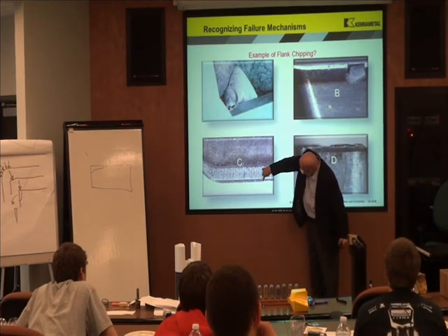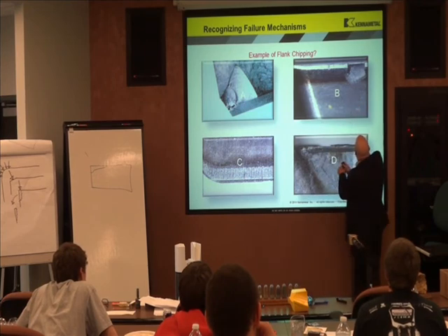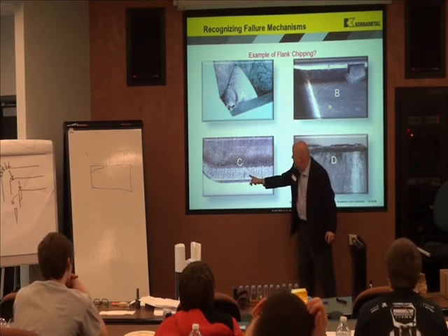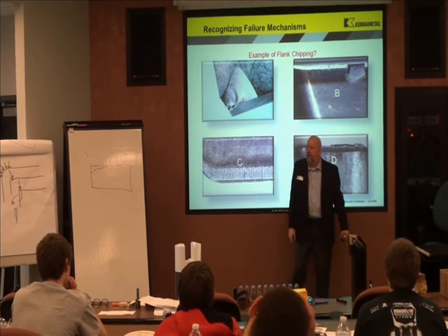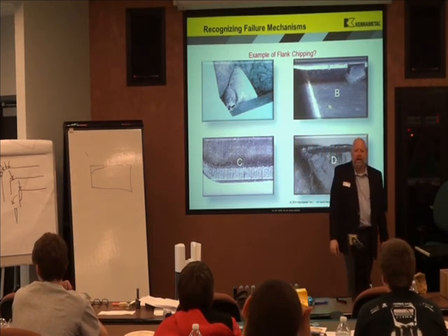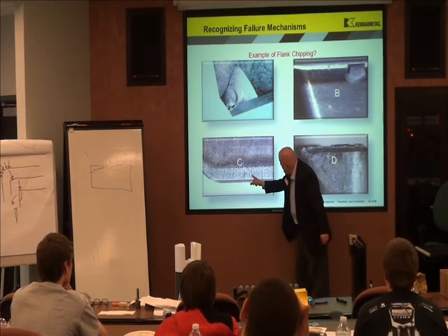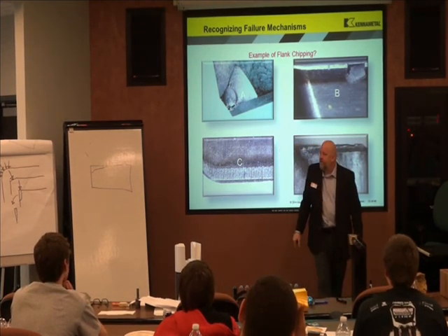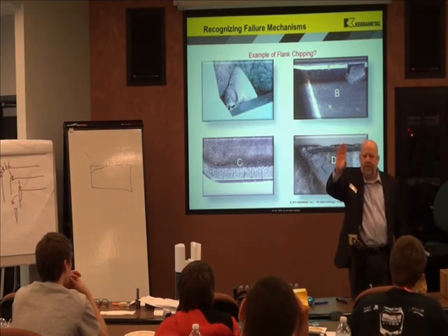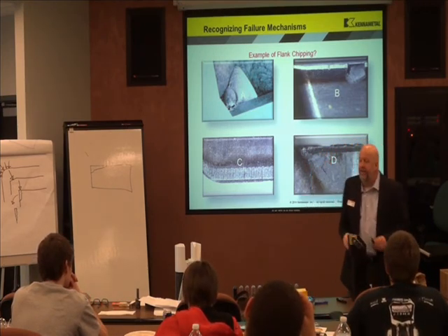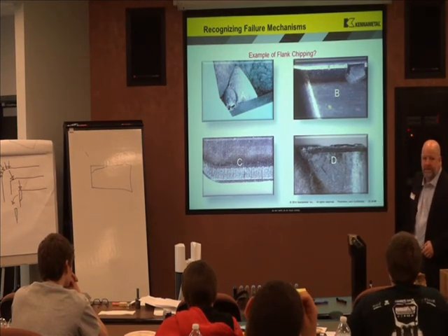This is that chip at the top right here. What was happening first? Thermal cracking. Those thermal cracks got so big that eventually it chipped.